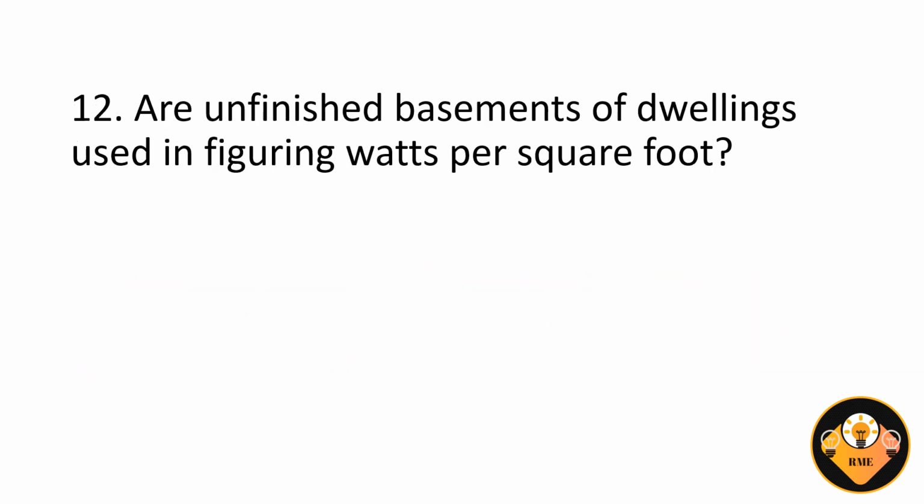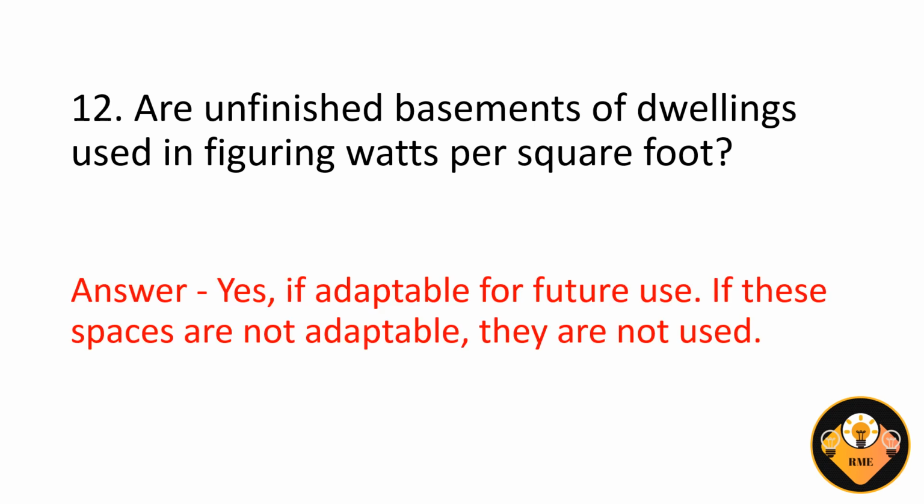Number 12. Are unfinished basements of dwellings used in figuring watts per square foot? The answer is, yes, if adaptable for future use. If these spaces are not adaptable, they are not used.